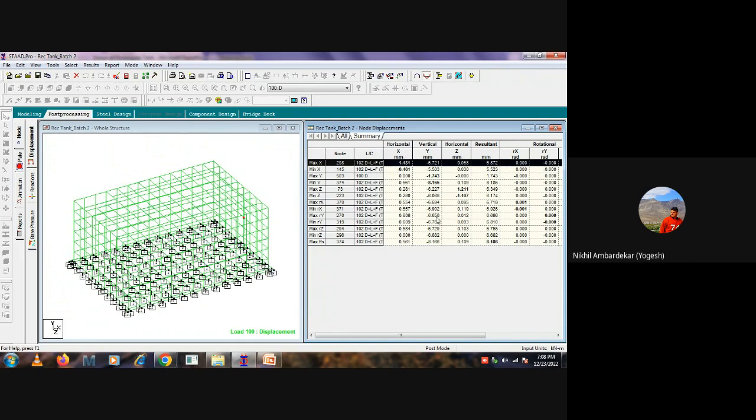Based on these values, by observation the deflections are okay. Same thing with the Z axis: the maximum deflection is 1.2 mm for this wall panel along the Z axis. For all walls the maximum allowable deflection is 30 mm, which is way more than that.